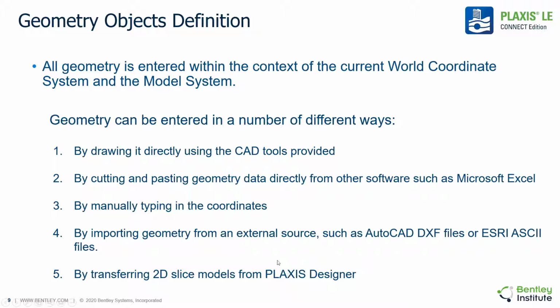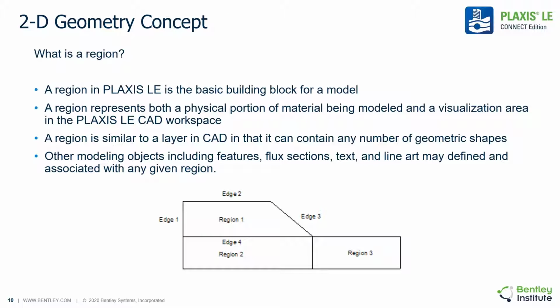Another option is transferring the 2D slice models from PLAXIS Designer in case the user has developed a 3D conceptual model. So what is a region? A region in PLAXIS LE is the basic building block for a model. A region represents both a physical portion of material being modeled and a visualization area in the PLAXIS LE CAD